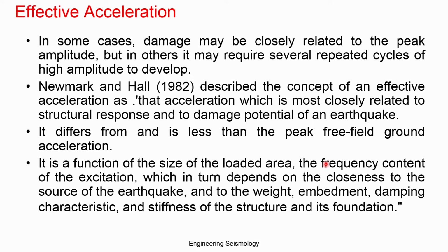Apart from that, we also studied the effective acceleration. In some cases, damage may be closely related to the peak amplitude, but in others it may require several repeated cycles. So, the repetition of the amplitude, rather than a single value, is taken into consideration, and they came up with the idea of defining the effective acceleration. Okay.